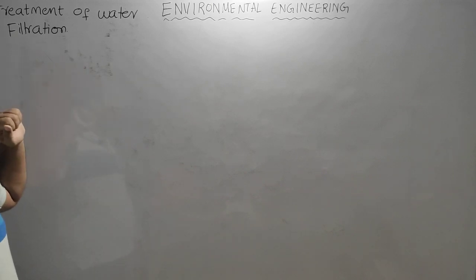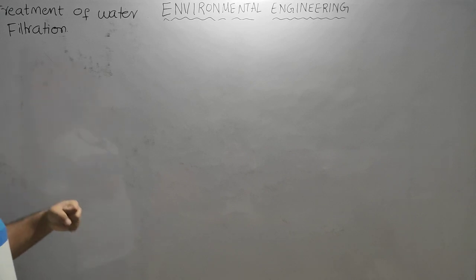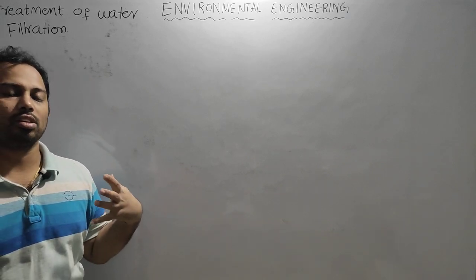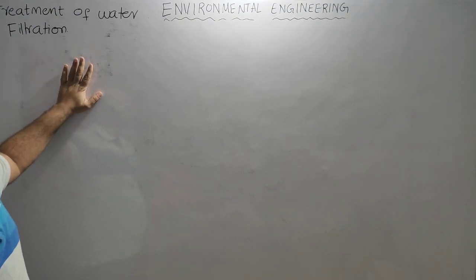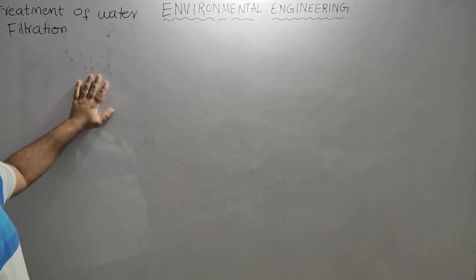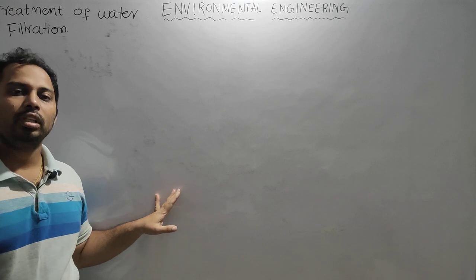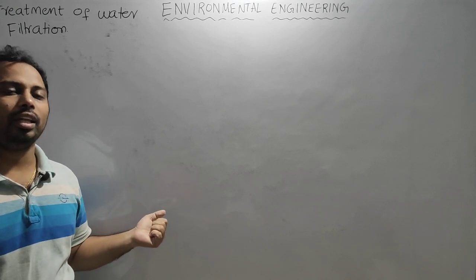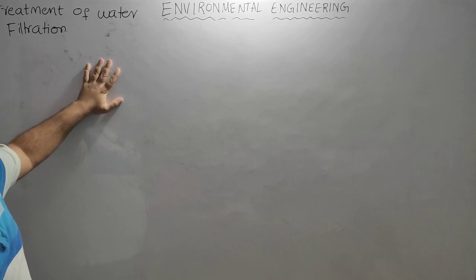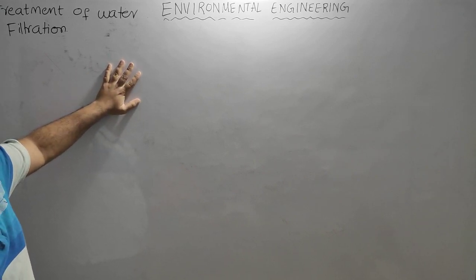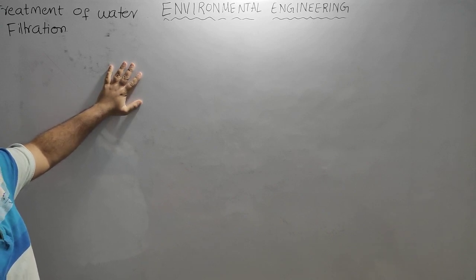This floc helps to remove color causing compounds such as iron ion and manganese ion. This floc sticks to the filter media and helps in removal of the color causing compounds. As this floc is absent in the water coming from the primary sedimentation tank into the slow sand filter, it is less effective in color removal.